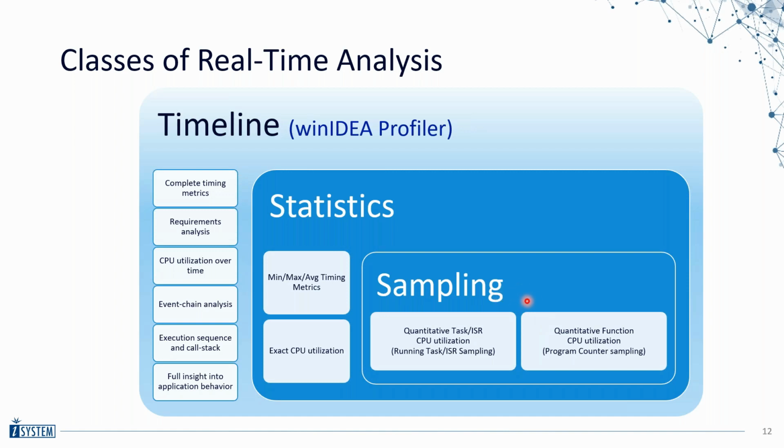And the nice thing about that is it's simple to set up. It doesn't take any special hardware besides your debug system that you have anyway. But what happens if you actually realize, oh, a certain task takes much more CPU load than I expected? The problem then with sampling is that you don't get any deeper insight into why this violation has occurred, okay? So that's sampling.